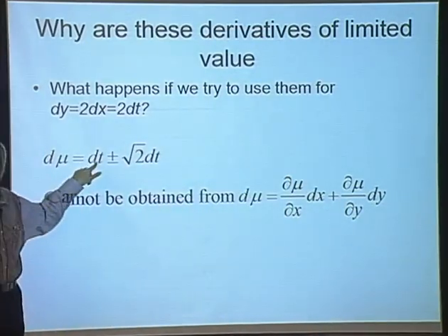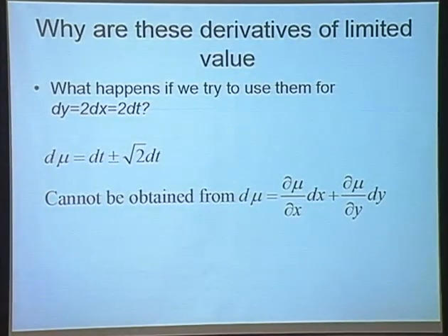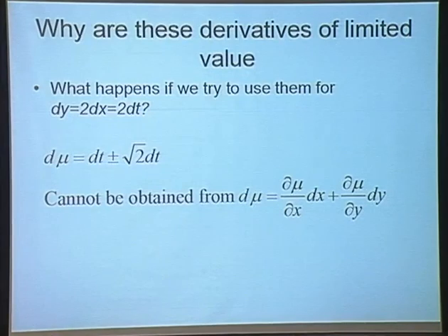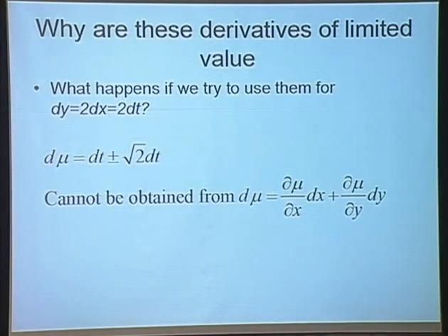There is no way we are going to get this answer by combining 1 and minus 1 for the first term, or 1 and 0. Remember that your finite element program is going to choose for you which one of the two it's going to give you, and no matter how it chooses, you're going to get no relationship to the true derivative in that direction.